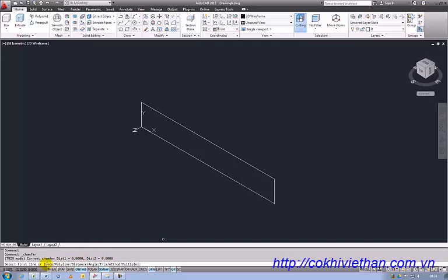And another good thing to remember is any options here that are associated with the command, anything that AutoCAD capitalizes, if we look at trim method, we can see that the T and the E are capitalized. So if we typed T and E, we would then get that option.